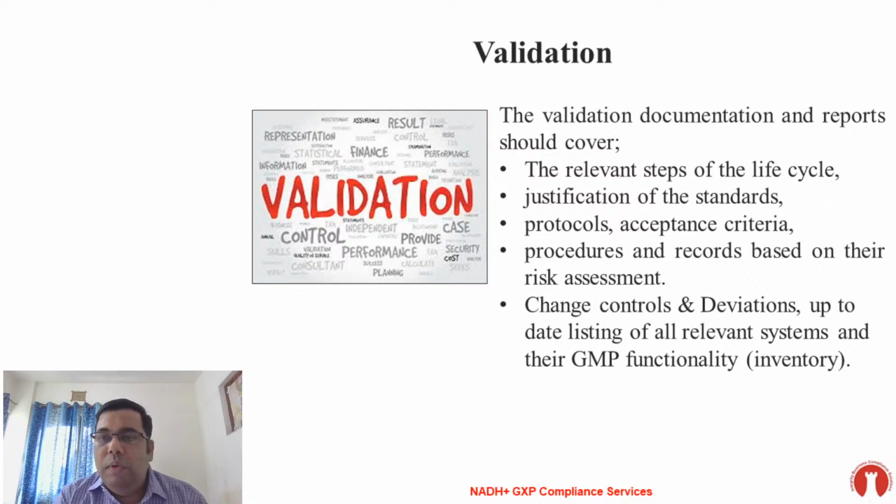This is very important because many people have this question, even in qualification and validation: sir, the vendor is giving this document, so are we supposed to prepare a new one again? My suggestion is you should have an SOP with a format. In the format you have to clearly evaluate and sign off whether the particular document is suitable as per your expectation and your company procedures or not. If not, then you should raise an addendum to that, along with the qualification or risk assessment or whatever you are doing with respect to the equipment or the software, and then that has to be fulfilled.